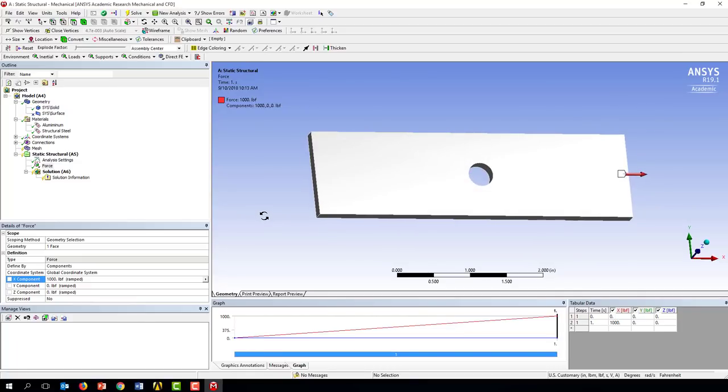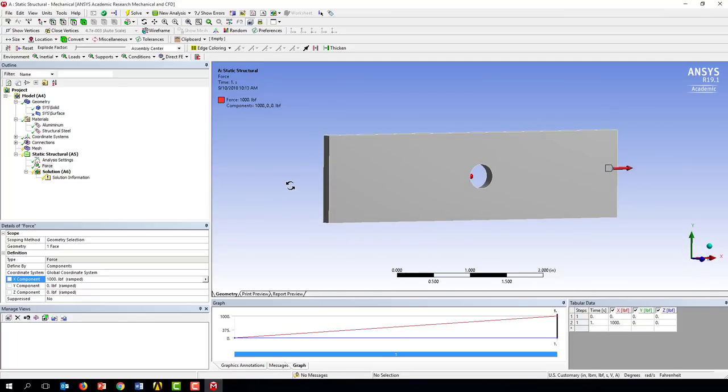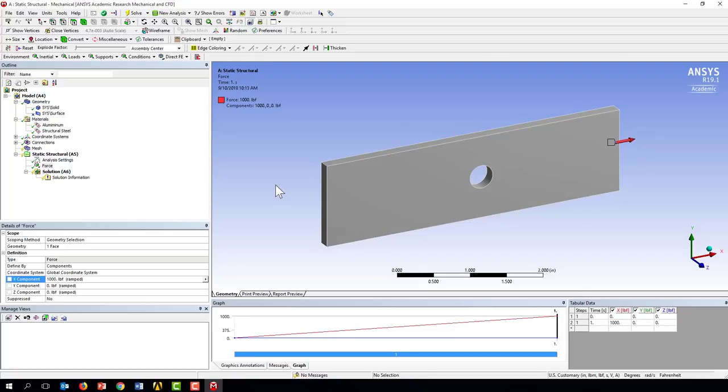Now, when we draw a model, we typically put forces on the other side, but that doesn't guarantee stability, right? If I have 1,000, and again, there's some rounding error, it gets a little bit unstable and it starts accelerating to infinity, which is a little inconvenient. And so instead, what we want to do is just apply a displacement boundary condition that would constrain it to be stable, so it'll have whatever reaction force is necessary. On this surface,